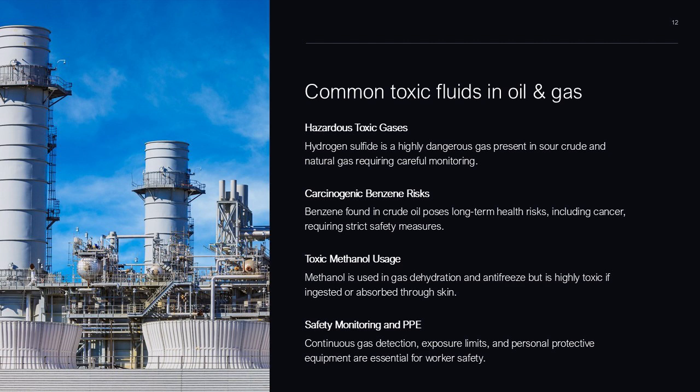Benzene, found in crude oil and refined products, poses long-term health risks including cancer. Methanol, used in gas dehydration and as an antifreeze agent, is highly toxic if ingested or absorbed through the skin. These substances require continuous monitoring using gas detectors, strict adherence to exposure limits, and the use of personal protective equipment, or PPE, such as respirators and chemical-resistant clothing.